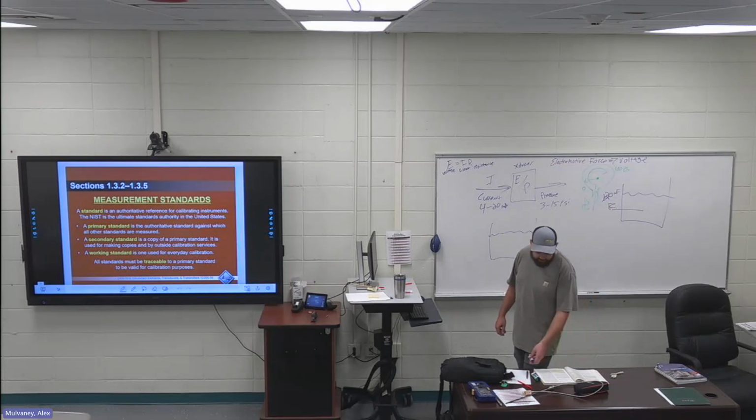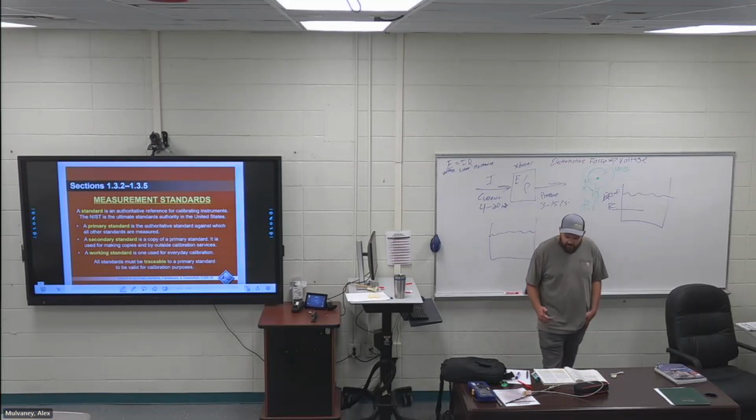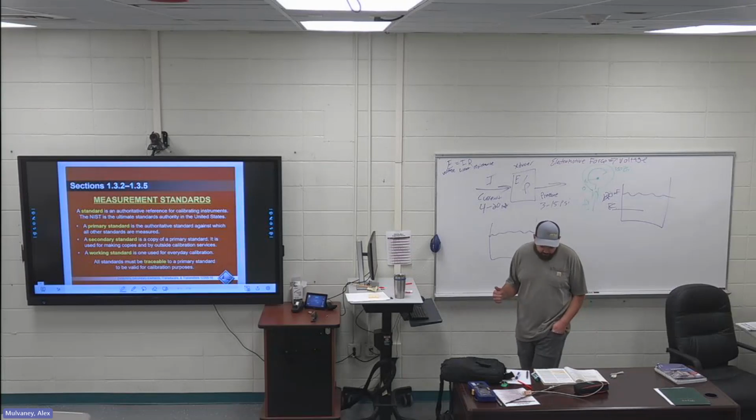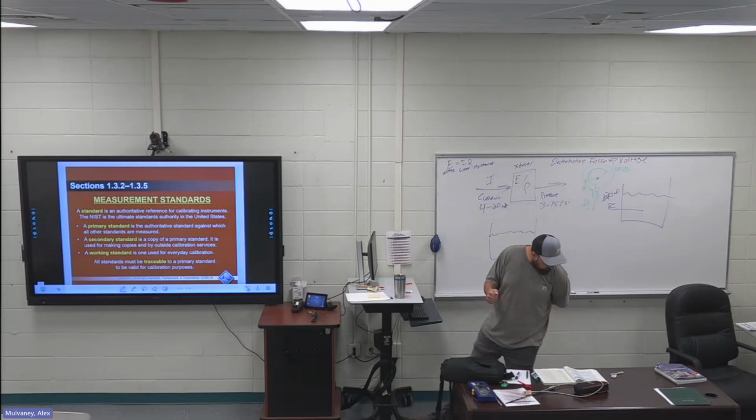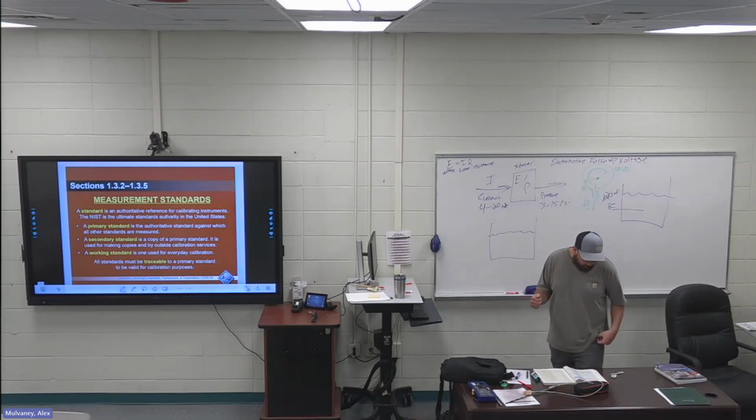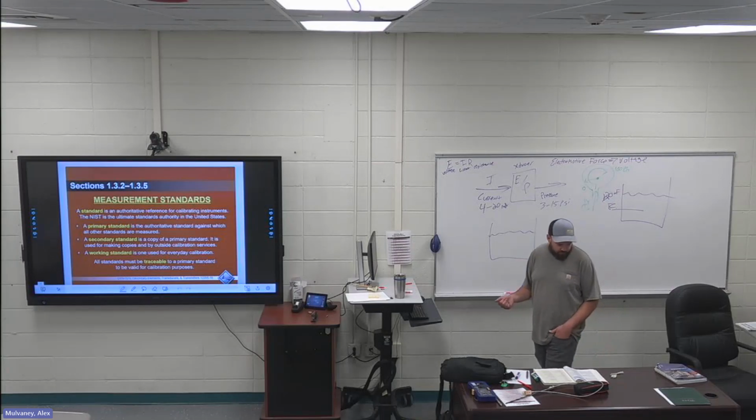I'm going to give you the next highlight that I'm going to talk about. Pretty much the entire next paragraph is highlighted as a separate highlight. Inferred measurement occurs when there's an indirect comparison. That is, a change in the process variable affects a characteristic or property of the material, the measuring system or detector. It's a change in the detector that's actually being measured. For example, when a certain temperature exists in the junction of a thermocouple, a voltage is produced. A voltage is the actual parameter being measured, and the temperature is inferred or derived from the characteristic of that voltage.